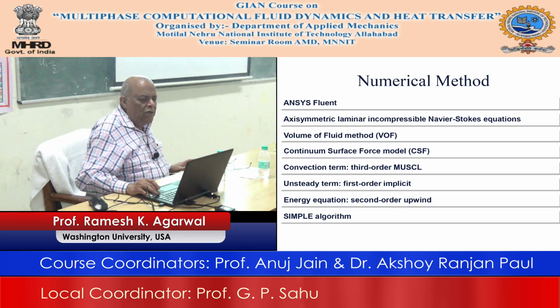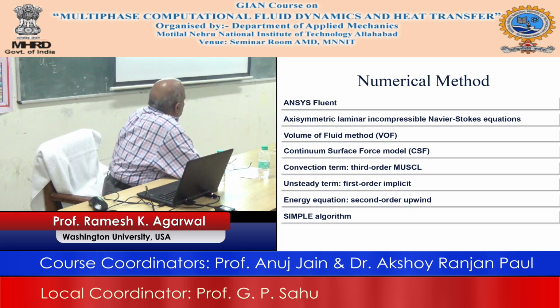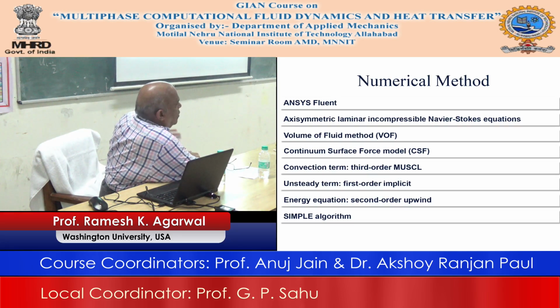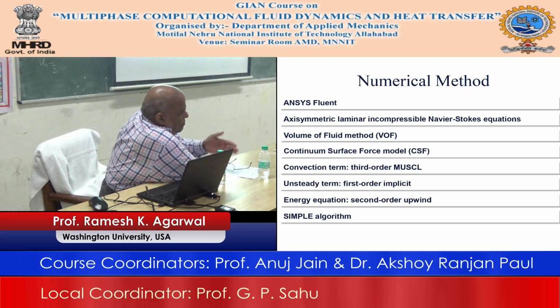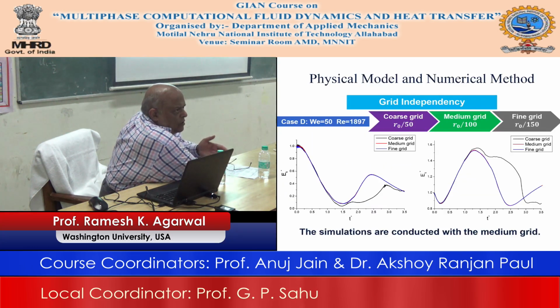Again, the procedure is the same. Once we have decided on the solver and various aspects of the solver, then we have to do the validation and also the grid independence study, the same kind of procedure in every case. You will see this even in the other cases that I will show you on cavitation and so on.